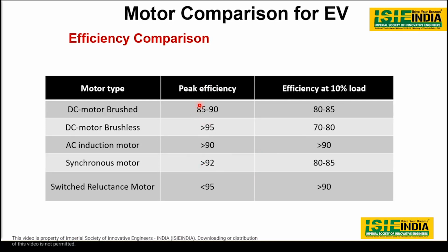This is what everyone will see. That is what Indian two-wheeler manufacturers today are projecting: peak efficiency is this much. Then the point everyone has to understand is what happens at 10% loading, 30% loading and 50% loading. This is what I am saying indirectly as powertrain loading. So the DC motor differs slightly at 10%. Why are we calling this 10% a light load condition?